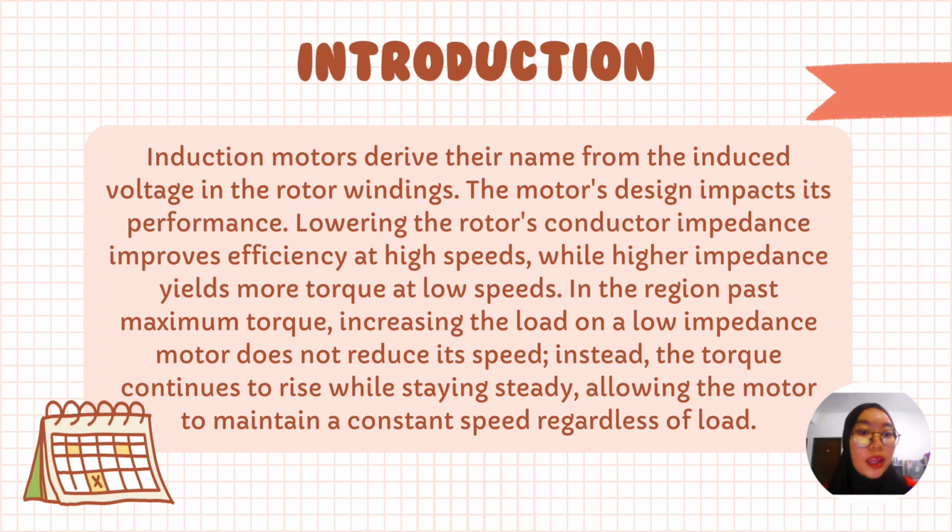Now I will present to you about the introduction. Induction motors derive their name from the induced voltage in the rotor winding. The motor's design impacts its performance. Lowering the rotor conductor impedance improves efficiency at high speed, while higher impedance yields more torque at low speed.